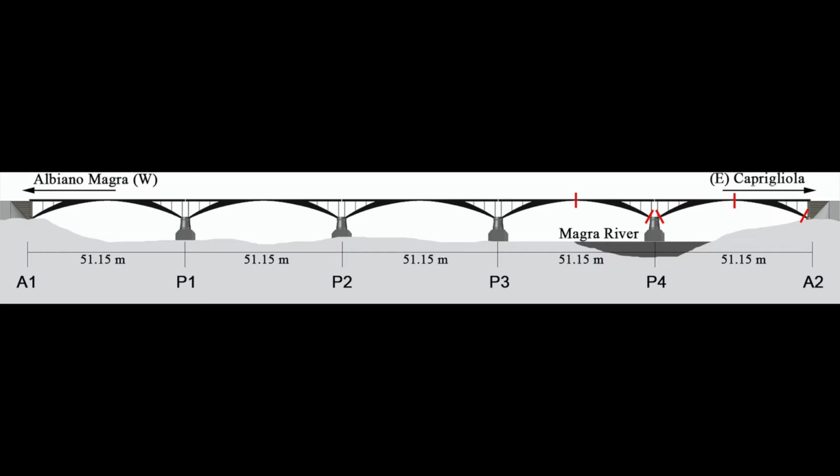So this is a diagram showing the predicted failure points for the bridge. They predicted it to be between Pier 3 and Pier 4, or between Pier 4 and the connection A2. You can see under Pier 4 the sediment movement that likely caused most of the failure.